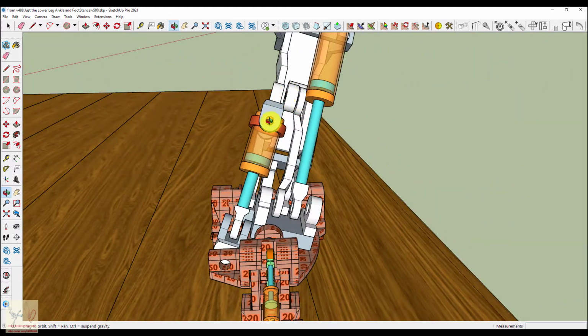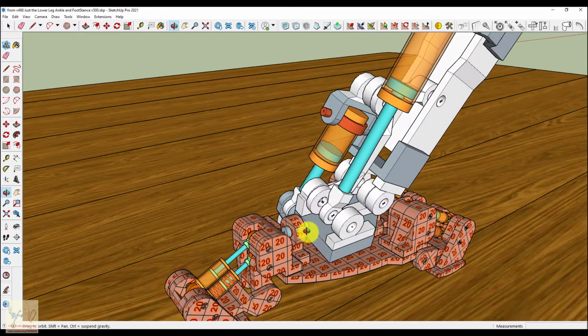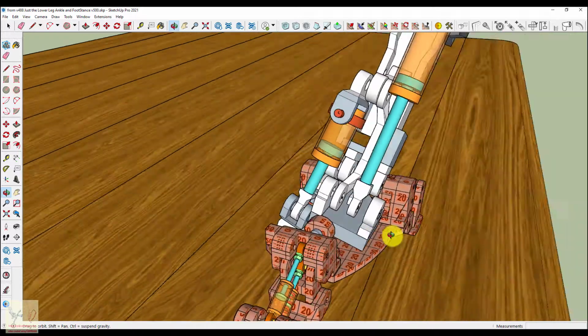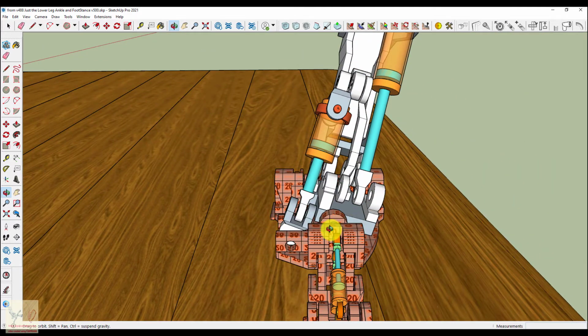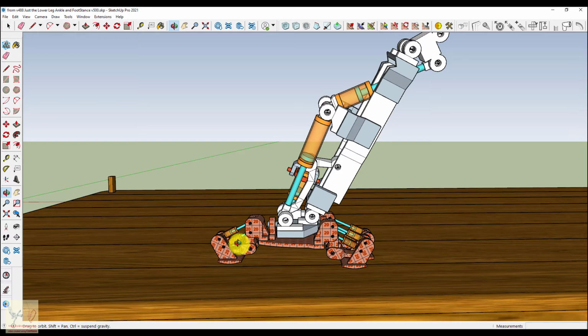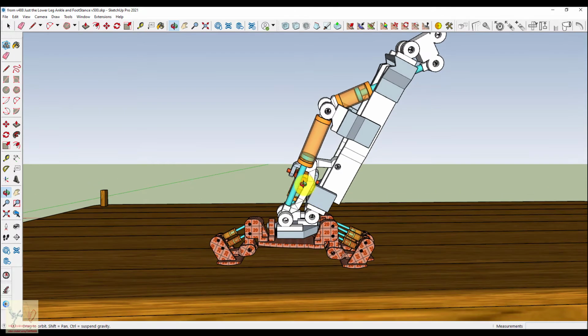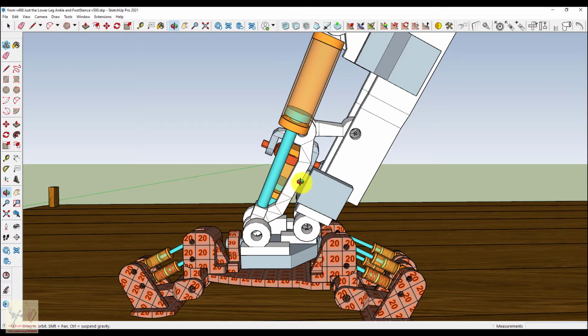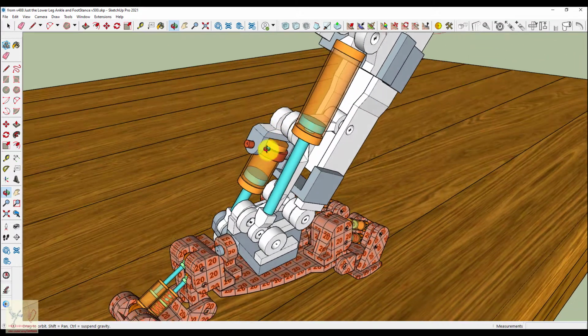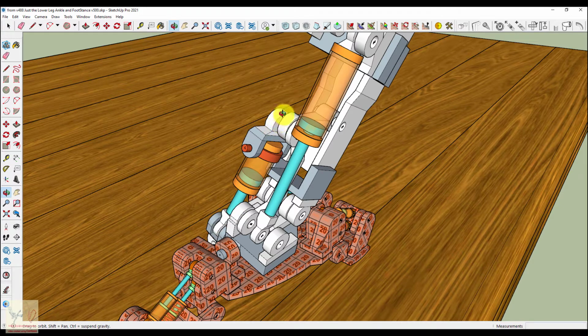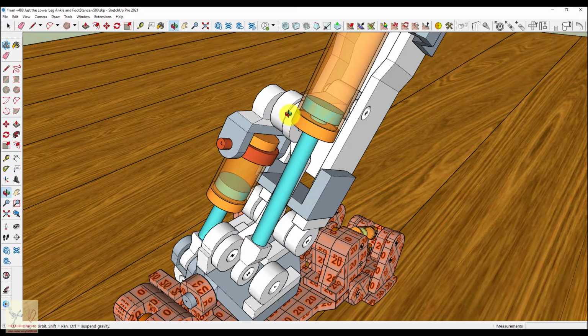And the independence of the eversion and inversion piston, anyway, it was always independent, means if you change eversion and inversion, it's simply rotating around this shaft here. The changing of eversion and inversion isn't going to have any effect on dorsiflexion and plantar flexion. And now, because of this linkage, the anchor point of the eversion inversion piston has been indexed to the piston that controls dorsiflexion and plantar flexion.